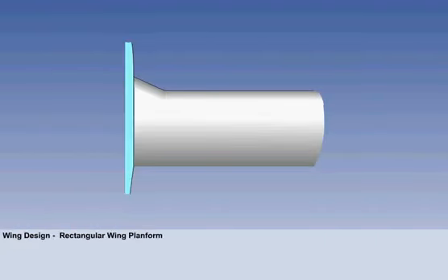As well as the wing's aerofoil section, its shape or plan form will also have an effect on how it stalls. On basic, conventional wing planforms, the separation that causes the stall will not occur simultaneously at all points across the wing.